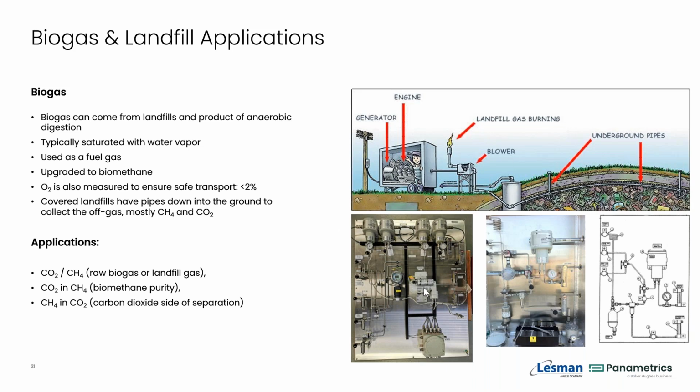In fact, if we were to look closely at this panel that has 3 thermal conductivity analyzers and an oxygen analyzer, you'll also see an H2S transmitter here, just to feed back the H2S measurement to the PLC. So in essence, no, there is no issue with the hydrogen sulfide or with corrosive gases. And in theory, we could use this to measure one gas in something like chlorine, for instance, as long as it's 1% levels of one gas in another. Again, it's just a matter of choosing the right materials of construction and keeping things relatively dry.